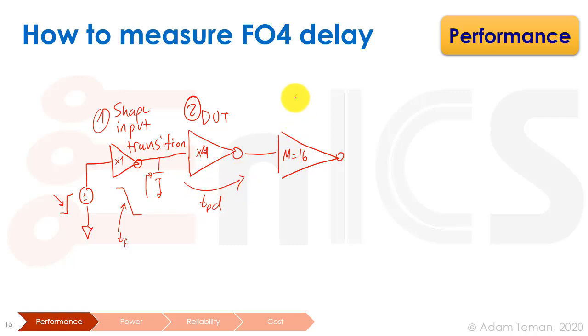Okay, our third gate, of course, is the load, but is that enough? And this is a good question. Well, what's going to happen here is, we're going to have our falling transition over here, and then this will rise with also something that is representative of the technology in the fan-out for load. But here we have very little load because it's an unloaded gate.